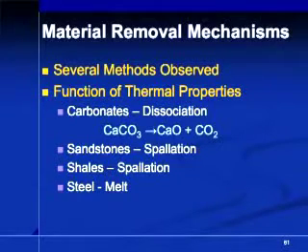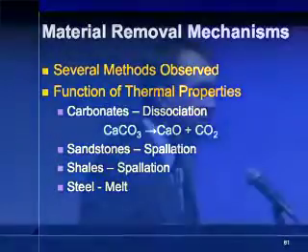Sandstone's a little different. You don't want to get above the melting point of the quartz and make glass, so you have to throttle a little bit, but what you do is you rapidly expand and contract the size of the grains, and they separate from each other and they sand apart and you make a hole. Shale, same thing, and steel, it's a solid structure, and you just melt it. So the same laser, same wavelength, same power can cut all those different materials.